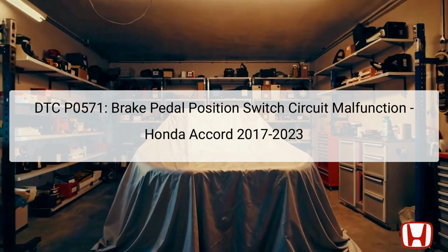If this switch fails or displays erratic behavior, it can lead to improper brake light operation and potentially unsafe driving conditions. This DTC is typically set when the brake pedal is lightly pressed for 5 minutes or more, while the accelerator pedal is also depressed, creating an electrical fault within the circuit connected to the switch. Therefore, addressing this issue promptly is essential to ensure vehicle safety and compliance with regulations regarding brake light performance.